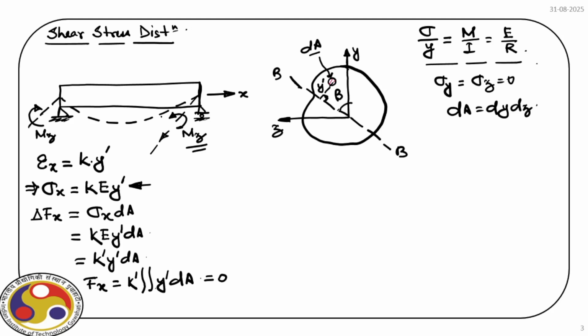In this case it is a sagging profile, so we have tension at the bottom and compression at the top, and the compressive and tensile forces should balance each other so that the net force is 0.